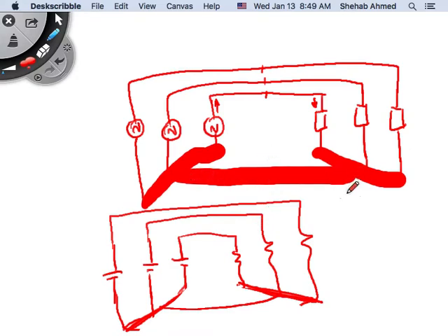But you still use 2 lines to connect the 3 resistors and the 3 generators. No, here, you mean here? These are not lines. This is a node in the circuit. I can bring these to the same bus bar, and I will screw to the bus bar, screw to the bus bar, screw to the bus bar. So this is just a node in the circuit. These are far away from each other. The generation is very far away from the load, right? So I eliminated 2 cables here, right?